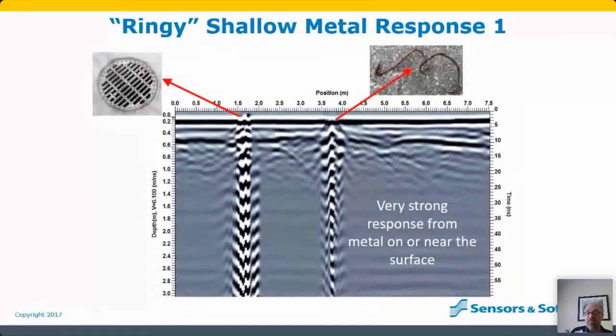And if you had a pipe that was a metal pipe that was 500 feet long, technically it would ring, but it would take so long to travel to one end and reflect from the other and come back that you would not see it like this. The reason you see this ring is because this metal is short enough that the energy can just go from one end to the other and turn into an antenna. So some of you more than likely have encountered things like this and wondered, what do I make of this?